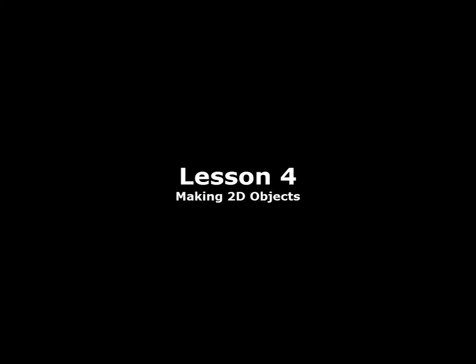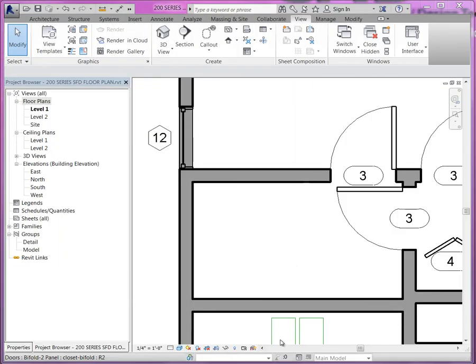Okay, so in this video we're going to take a look at developing our 2D drafting views, and we're going to take a look at using detail lines and model lines. We'll take a look at how to develop these 2D drafting views and then use those drafting views to create 2D grouped detail lines. We'll take a look at how to use these in the floor plan view, how to ungroup them and convert them to model lines, and then regroup them.